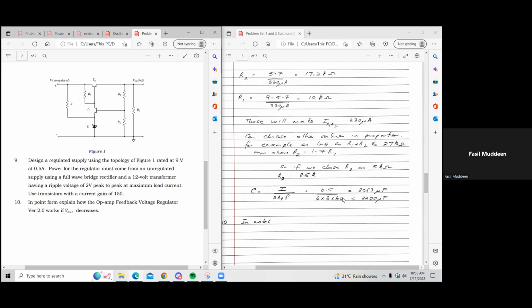This kind is a little more complex, and then of course if you put in the third resistor for overcurrent, whether it's foldback or just straight current limiting, then you have a little more calculation work to do.